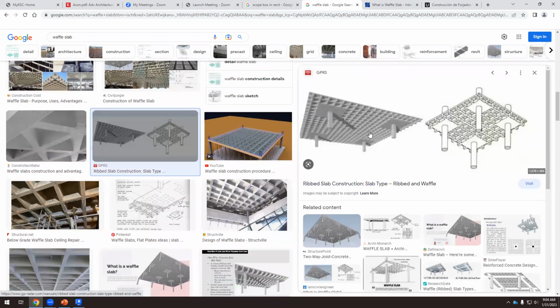So if we want a ceiling that is exposed concrete, we can use this waffle slab with reinforcement where the column is. And if by calculation we need a solid slab, we have to use solid slabs. So there are some aesthetic decisions. This is probably the most beautiful one. Then if aesthetics don't matter because we're going to hide the ceiling with a false ceiling, the one-direction joists and the bolts, probably this is the cheapest. But when we have heavy loads on the building, we might need a solid slab. Anyway,